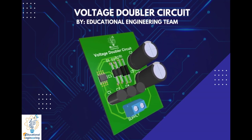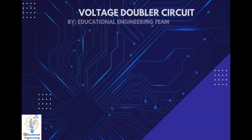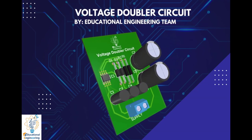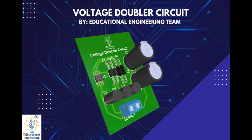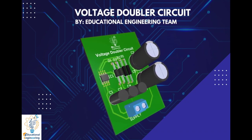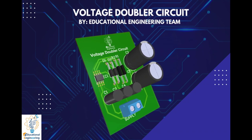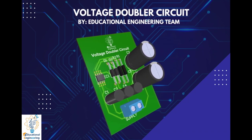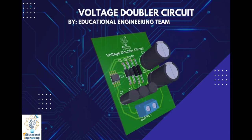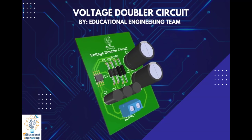In this circuit, the IC555 is wired as an astable multivibrator and it gives continuous square waves as an output. The IC555 serves as an oscillator for the entire circuit and was wired to generate a square signal of frequency of about 2 kHz. The frequency of the astable multivibrator depends on the resistor and the capacitor. This makes the output voltage to be doubled from that of the input voltage source.